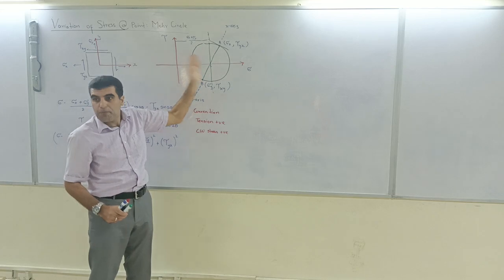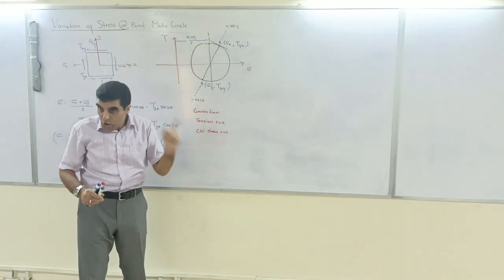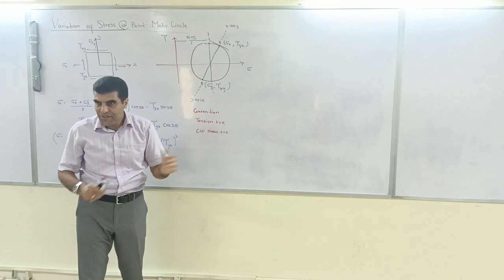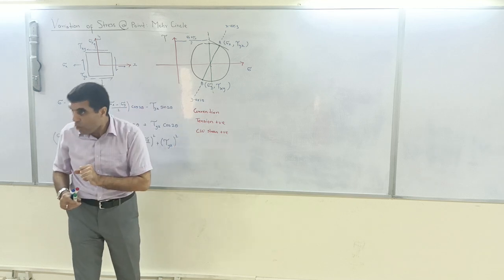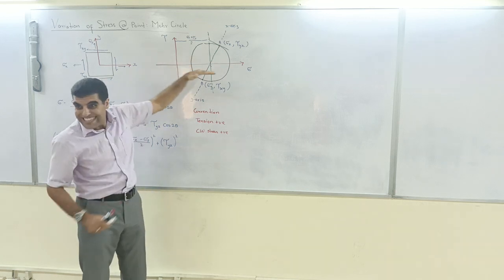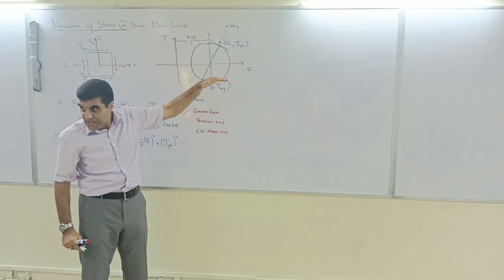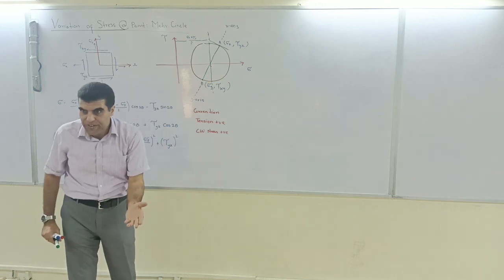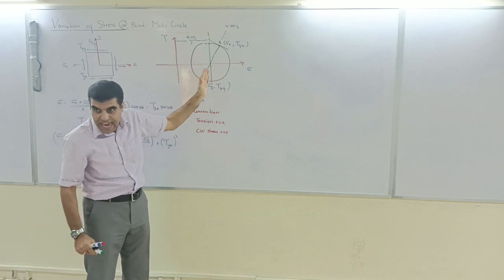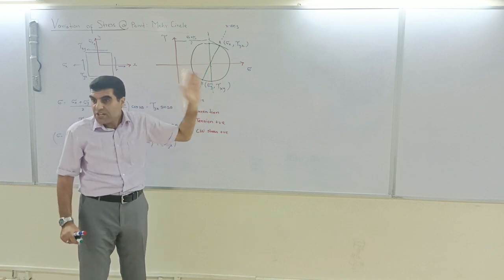So at the point of maximum shear stress, you in this case have axial stresses. There is a difference, please note, I'm again repeating. At the principal stresses axis, you don't have any shear stress, but at the maximum shear stress axis, you have axial stresses.